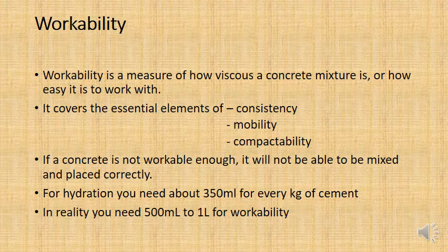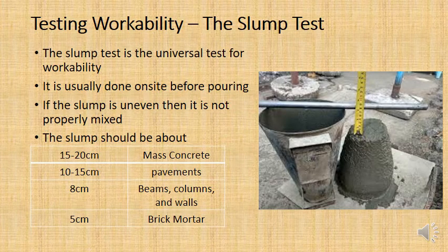So that's workability. How do we test workability? Well, I don't know if you've ever seen this, and I don't know if any of you have actually ever made concrete before. Hopefully at the end of this semester, when we're all back at the university and the quarantine with coronavirus is over, we can do this test, we can make concrete together. But the test for testing workability is the slump test.